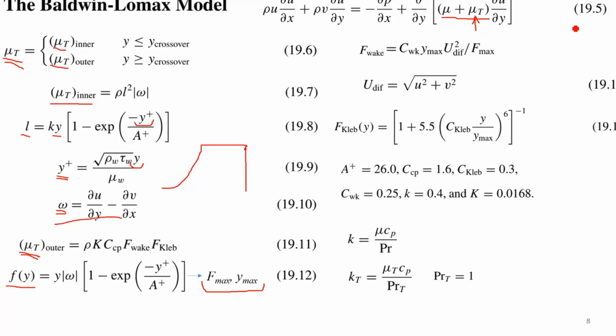As before, to solve this problem, we must set boundary conditions, as I told you, for laminar or for general discussion, which we had in the previous lecture. We must set zero velocity on the wall, right? Known temperature on the wall or known heat flux on the wall. And with these boundary conditions, we obtain the whole flow picture.